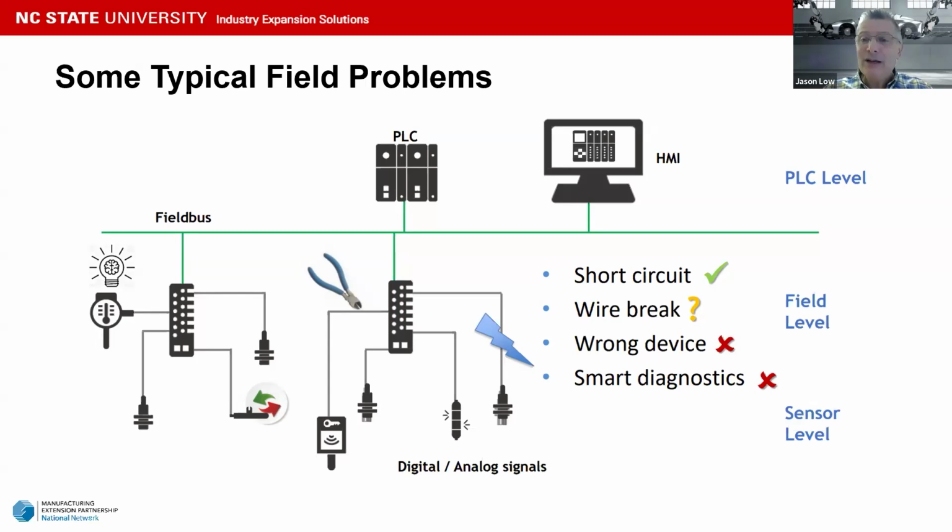In a control system, we may not know that right off, or we can't even drill down to figure out what the sensor is in an immediate fashion. So these sensors monitor their own health and can send that information to our control or to some other device to let somebody know that a fork truck driver just drove over this cable and is rendering this device either inefficient or not able to communicate anymore. So these are troubleshooting things as well.